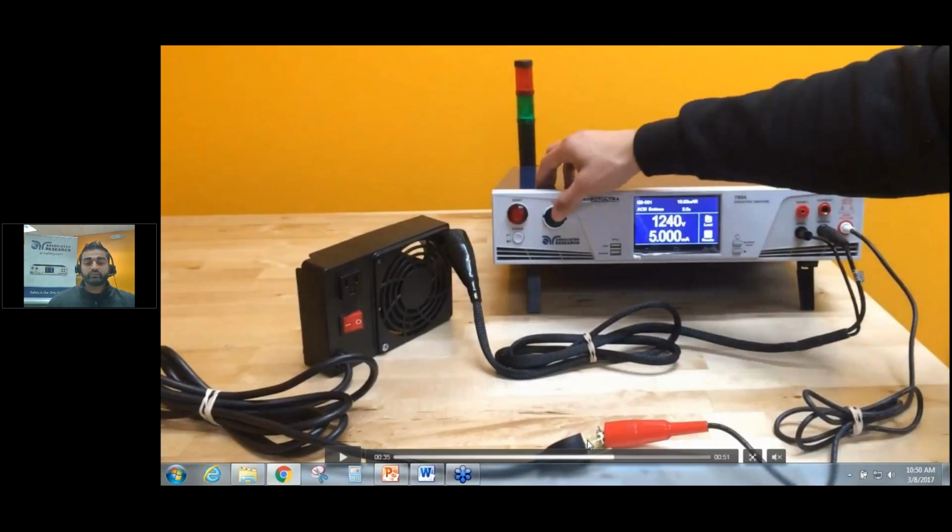We also sell adapter boxes that plug directly into our instrument without needing line and neutral to be shorted, but I just wanted to show you an example of what's being tested. You're applying high voltage where normally it's only going to see 120 volts or 230 volts, and you're making sure nothing breaks over to the other side, arcs over to this metal screw, because this metal screw is there so that if somebody touches it, they don't get shocked at that metal point. So you want to make sure there's enough insulation around your line and neutral that doesn't cause any electrical shock hazard.